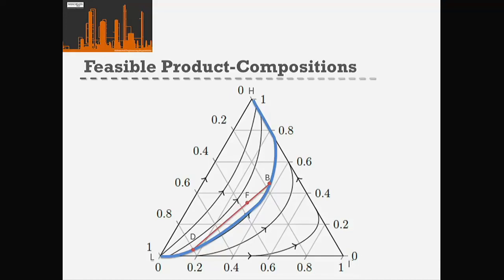And if you think back to liquid-liquid extraction as well, we could use the lever arm rule on the points on this straight line to find the total flow rate of our distillate and the flow rate of our bottom product. Okay?